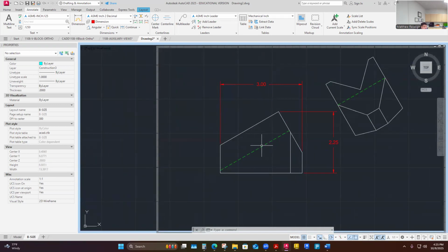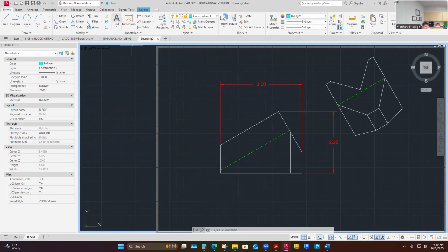So this front surface, let's consider its size. Its location is maybe a little bit more vague. I'm not locating to a coordinate point, and I'm not locating to a center line, so its location is just going to be as it is. I'm thinking of its size though, for sure. I've got the overall height of that. I don't really have the overall width of it, because that's really the overall part, including some foreshortened surface. So let me just focus on just this one surface here, which is relative to the back as it is the front. It has some geometry that I don't have dimensions for.